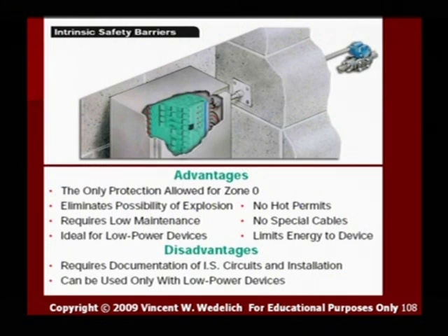Here we have an intrinsically safe system. So here we have a device inside this enclosure that limits the actual energy so that you can never have an explosion. It actually limits the ability to create an arc. So the advantages are it's the only protection allowed for zone 0, eliminates possibility of explosion, requires low maintenance, ideal for